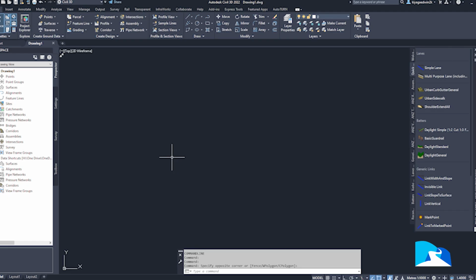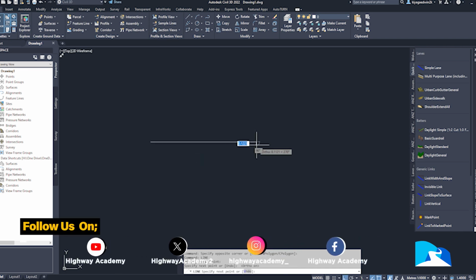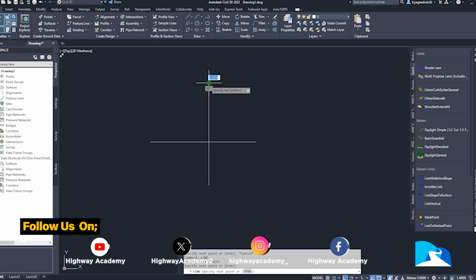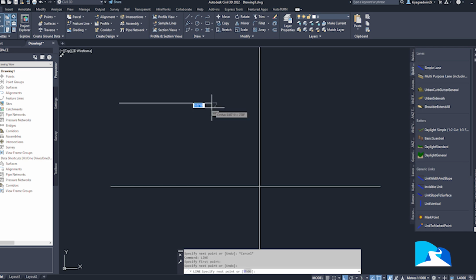Okay, today I'm going to be talking about some of the commands you should know that we should use in Civil 3D. Okay, some of these are just basic AutoCAD commands, so I'm going to just highlight a few of them. Okay, one is a trademark, is you should know how to extend a line. So for example, if you have a line there and we want to extend it up to here, so we select the line and then we click extend. Okay, but then at the same time in Civil 3D 2022 they made the extend command much easier. So if you select this and then you just select this, it just extends. Okay, you don't have to keep selecting the edge.